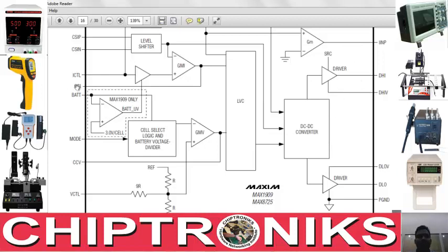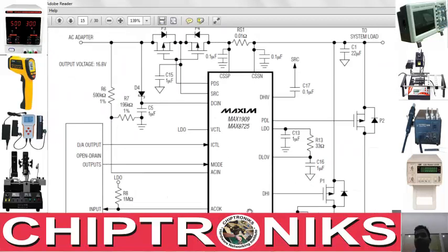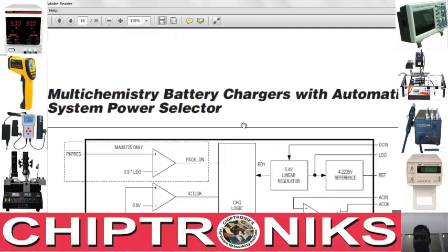So this ICTL is an input from the IO controller, and this Maxim charger generates two outputs. What are those two outputs? One is ACOK, which is a digital signal to the IO controller, which shows the presence of adapter, and IINP, which is the input current sense monitor. And you can see IINP over here, how it is connected.